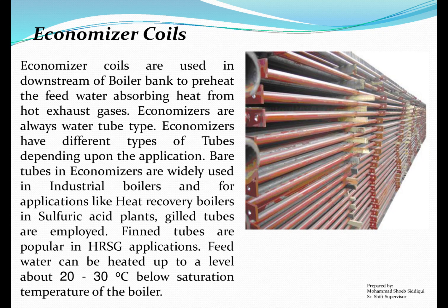Economizer coils. Economizer coils are used downstream of the boiler bank to preheat the feed water, absorbing heat from hot exhaust gases. Economizers are always water tube type. Economizers have different types of tubes depending upon the application.